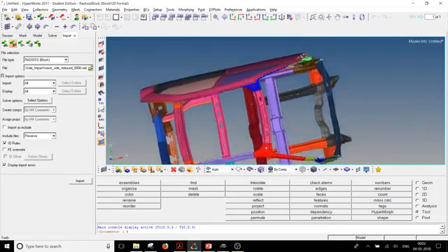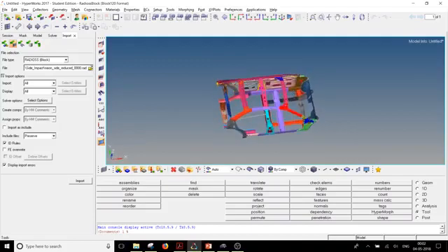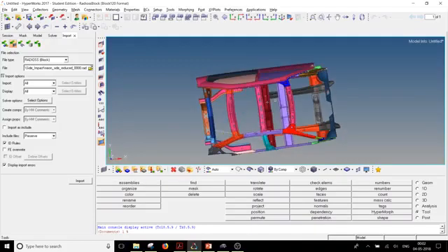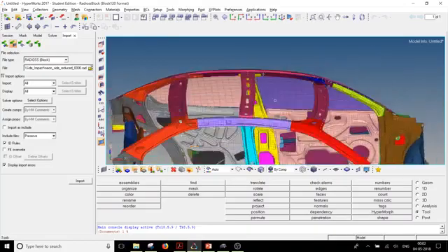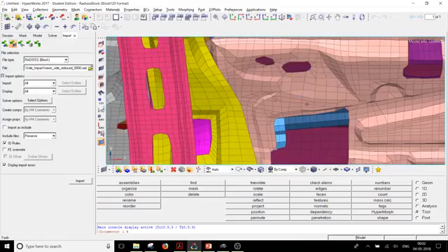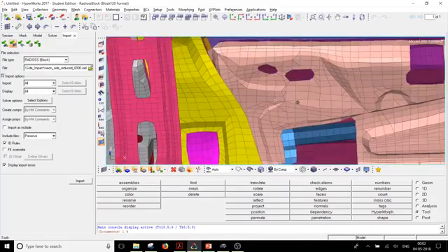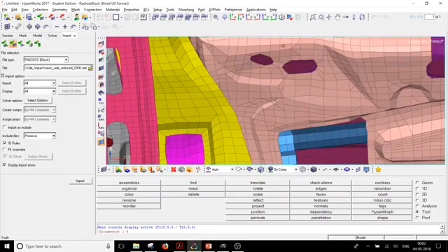So obviously your car is going to impact a pole impactor, or rather the pole rigid wall here, that is a cylindrical rigid wall. Your car is going to impact into the rigid wall, and there is going to be deformation on this side. Now if this deformation reaches the inner side, I want to see at what velocity the node over here is moving.